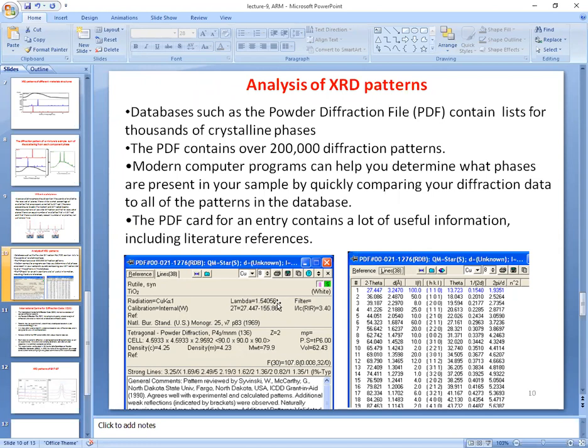There is Rietveld analysis, there is synchrotron data, and similarly we can obtain temperature dependent XRD also, which shows how the diffraction pattern changes with changing temperature. If you have a material and there is a facility for temperature along with the detection of the XRD, you obtain recordings at different temperatures.